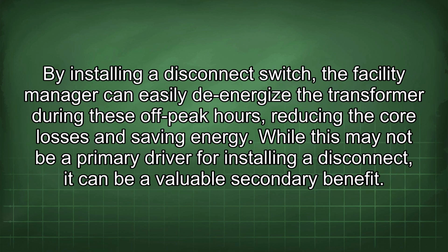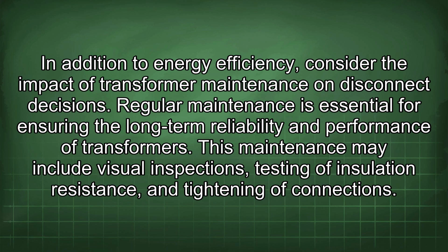By installing a disconnect switch, the facility manager can easily de-energize the transformer during these off-peak hours, reducing the core losses and saving energy. While this may not be a primary driver for installing a disconnect, it can be a valuable secondary benefit. In addition to energy efficiency, consider the impact of transformer maintenance on disconnect decisions.